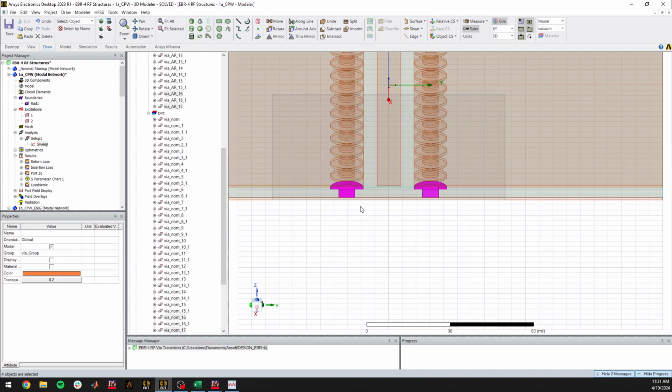We're not solving with any sort of copper or different platings, or things like ENIG plating with a nickel and gold stack up or anything like that. But this is necessary. Otherwise, the risk is it will solve the structure like a parallel plate structure, and you'll be getting a different mode relative to the pseudo TEM mode that you're looking to achieve with a coplanar waveguide.